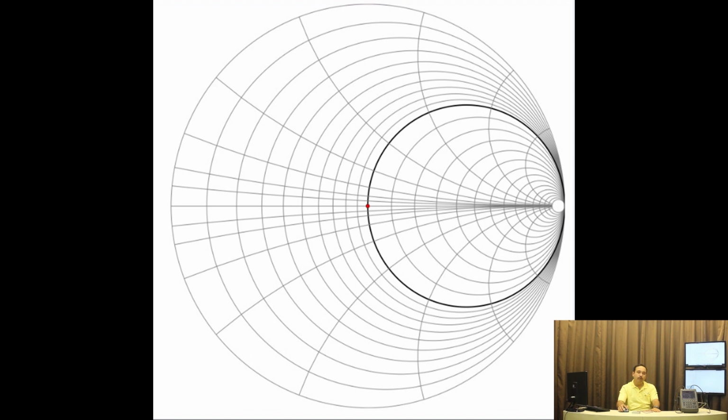What you have on the screen now is a Smith chart which I have plotted. Exactly at the center of the Smith chart, the red dot indicates zero reflection, and if our system reference impedance is 50 ohm, the impedance is also 50 ohm exactly at the center. On the upper side of the Smith chart, the impedances are inductive in nature with some positive real part,